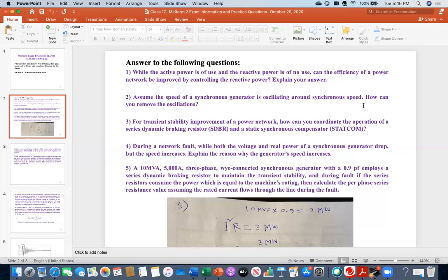There is a controller there. So does it come with the generator, or do we have to add it externally? No, it comes with it, but it is automated. For example, at the start of the synchronous machine, the damper winding will help you start. Then once the motor has started rotating, it will be taken out of the circuit. It will not be available in the circuit. It will be disconnected from the circuit. Now that thing is automated.